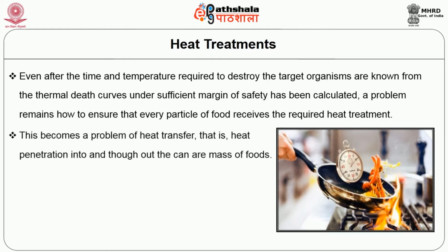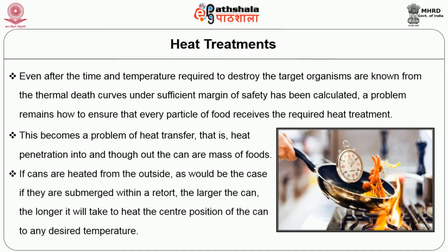This becomes a problem of heat transfer, that is, heat penetration into and throughout the can or mass of cans. If cans are heated from the outside, as would be the case if they are submerged within a retort, the larger the can, the longer it will take to heat the center portion of the can to any desired temperature.